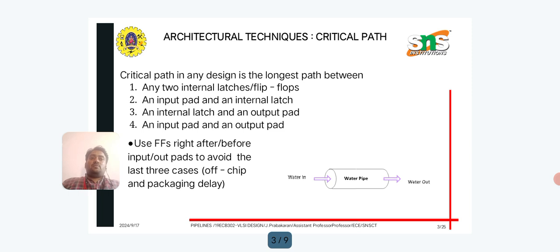In VLSI design, pipelines in sequential circuits are a critical technique used to improve performance by increasing the throughput of a system. Pipeline architecture is widely used in digital systems, especially in processors, to allow multiple instructions or data elements to be processed in parallel, leading to high efficiency.